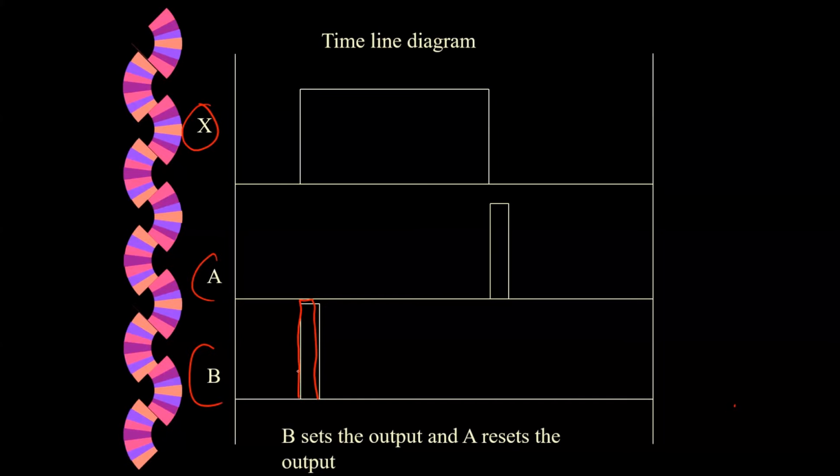It doesn't have to be continuously true. On the triggering edge, leading edge, okay, A becomes true and it doesn't care when this goes down. It can go down after some time or it can go instantaneously down, but A will keep alive. Okay, then B comes on, at the rising edge of B this collapses.